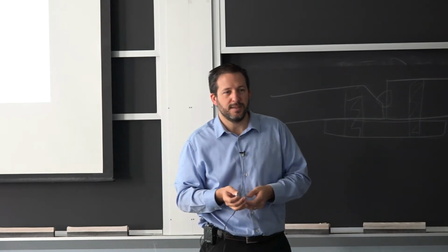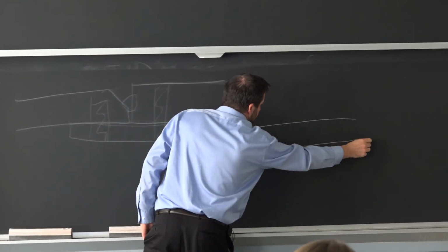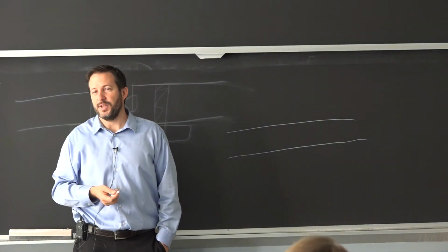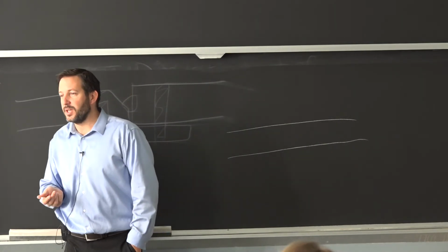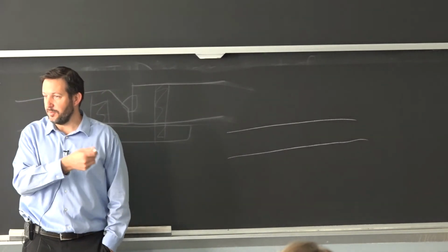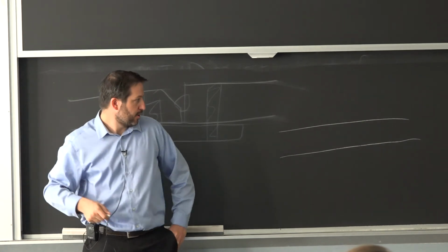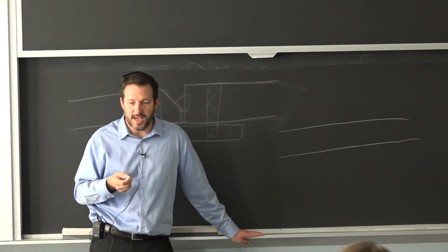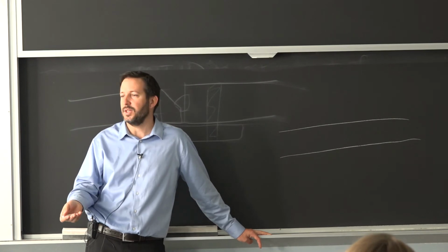So let's say the steel you use in the first place was not completely clean. So I start here. This is my plate. Turns out it was a piece of a bridge or anything. It came out of another guy's shop. It had some oil on it. Clean it a little bit, maybe, but it's typically not done perfectly. It's going to have a mill scale. So you go and start arcing against it. So you melt a little bit of that surface, and you melt the electrode. And really what happens is contaminants do have the time, because it's so high temperature that diffusion is strong, they have the time to get to that slurry.